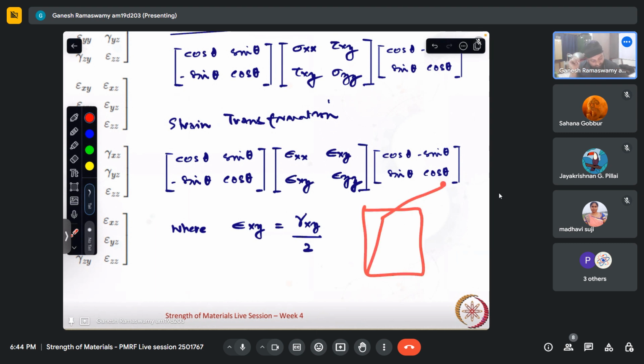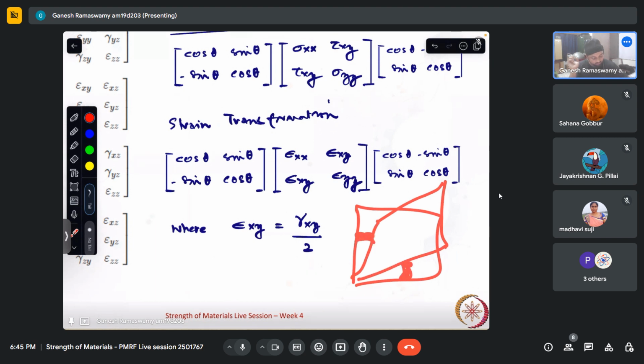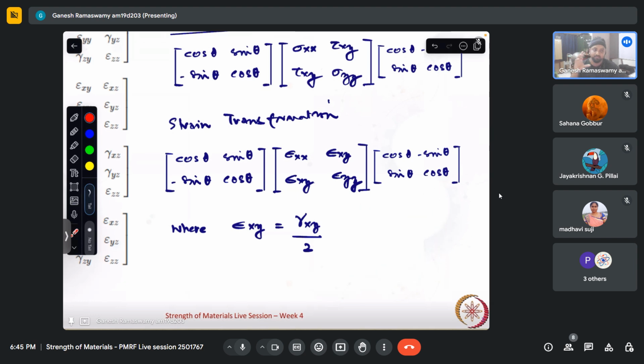It actually is the sum of these two. So when we go for strain definitions, this quantity and this quantity, although equal, is the sum of two sub quantities. That is, when this gets transformed, this is theta 1, this is theta 2. So tan theta 1 plus tan theta 2 essentially makes up the entire shear strain gamma xy. But this has to be distributed into two components and given to the strain tensor, which is when it will get transformed.